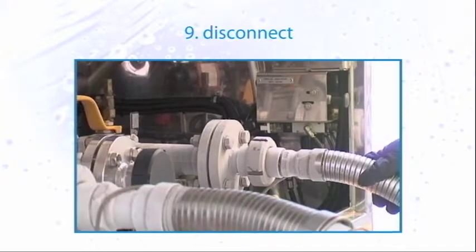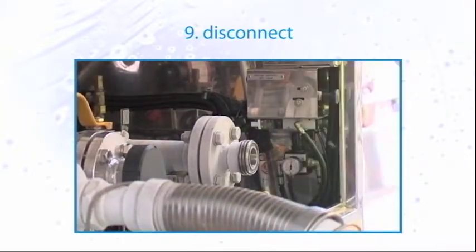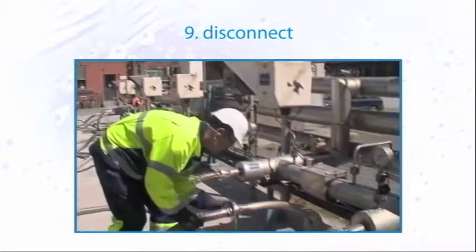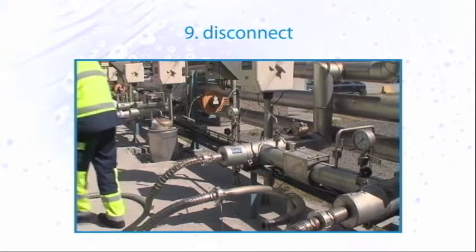This is a critical moment. If you do not do this correctly and carefully, an ice lump can form in the liquid hose during disconnecting and a projectile can come free. This is, of course, dangerous.